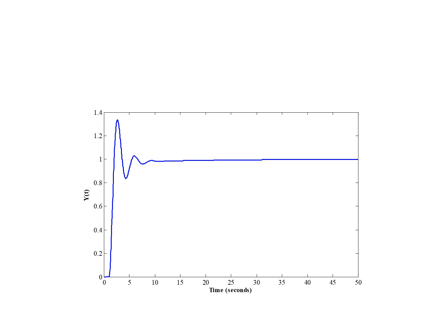See, our input is 1. So it settles properly. Okay. So this is how we are to tune. So once again, we'll revise. What's the first thing you need to do? You have to conduct the open loop test. How to do that? Open loop test.